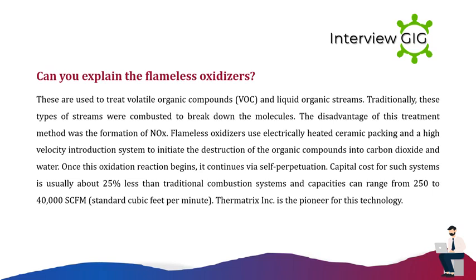Flameless oxidizers use electrically heated ceramic packing and a high-velocity introduction system to initiate the destruction of the organic compounds into carbon dioxide and water. Once this oxidation reaction begins, it continues via self-perpetuation. Capital cost for such systems is usually about 25% less than traditional combustion systems and capacities can range from 250 to 40,000 SCFM, standard cubic feet per minute. Thermatrix Inc. is the pioneer for this technology.